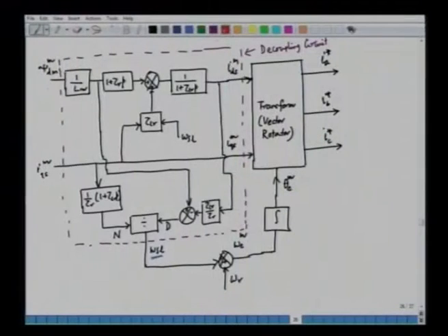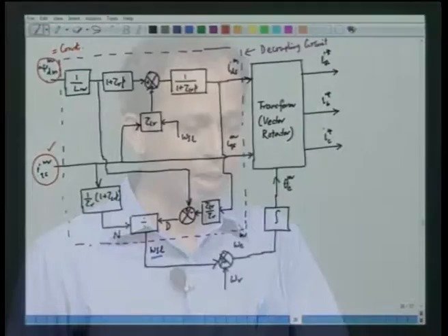can be maintained constant. So, if you want to keep the flux constant, we can say that this is our flux, and this remains constant. We can keep this constant and go on changing the torque component of current. This is our torque component of current. So, we can change IQS, and if we give a constant flux command, the flux will be constant, because this decoupling network or decoupling circuit takes care of cancelling the coupling present inside the machine.